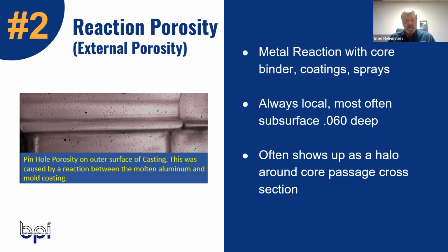But very much surface related. It's interesting because on this casting shown here you have a reaction with the mold, but on a sand core you have a reaction with the core that's going to show up on the internal surfaces of the casting. So it's critical, as Ernie said, it's surface related. If you were to take a cross section through, you're only going to see it very close to the surface. It's not going to be internal. So typically it's a finite type of porosity. It doesn't leak or anything. It's just what you see is what you have. Okay.